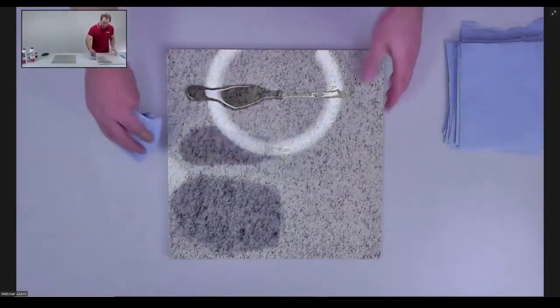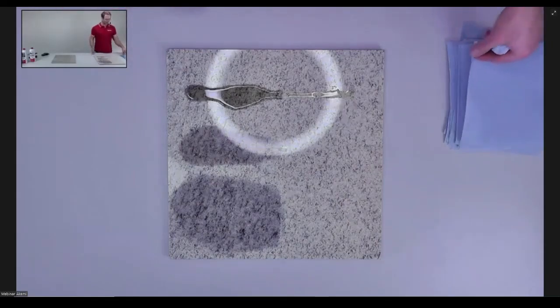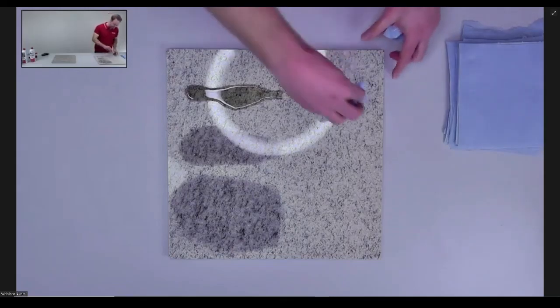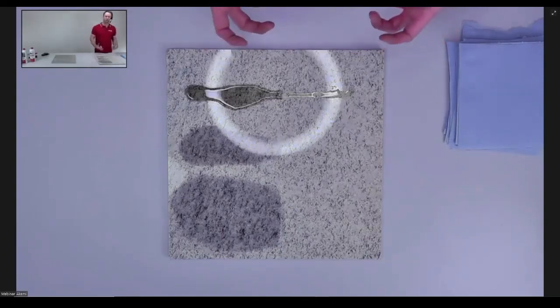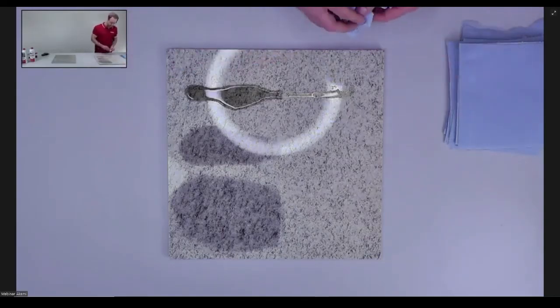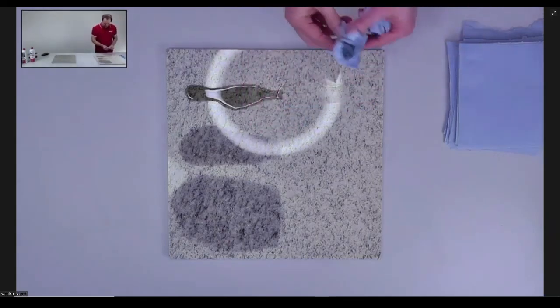This you can avoid with a proper treatment on a dry stone. This is always important. The stone must be dry. Apply a lot of material, a lot of impregnation. Not that we want to sell more, but the effect is much better. If you apply a good amount of sealer on top of the stone, you're sure it gets absorbed enough, and your stone will be protected the best possible way. The same with the oil here. Again, for the pearl impregnator, not a problem at all.